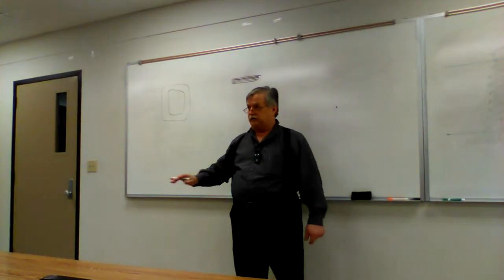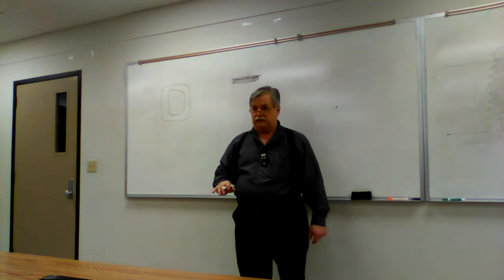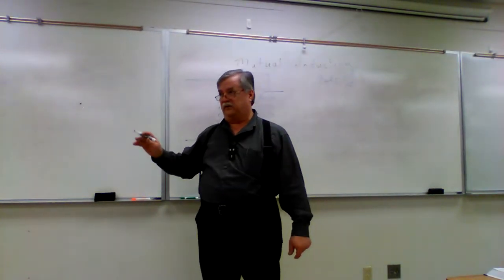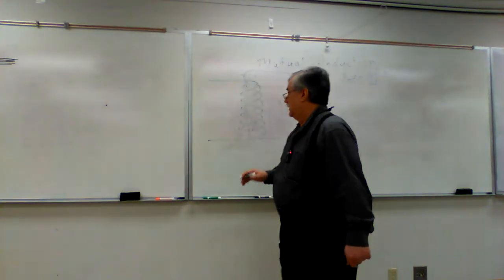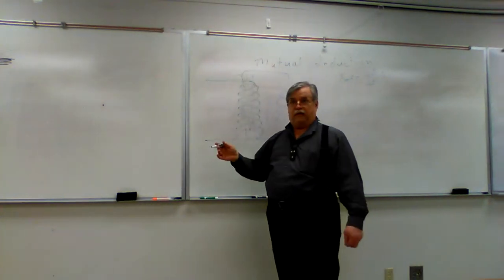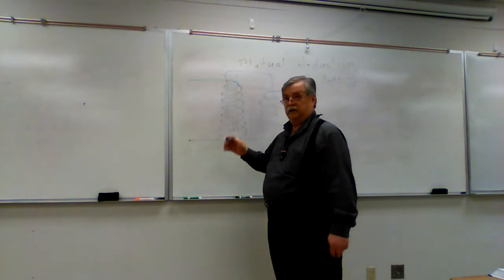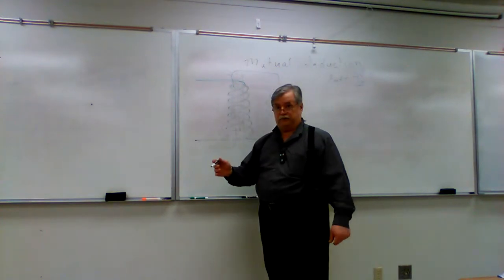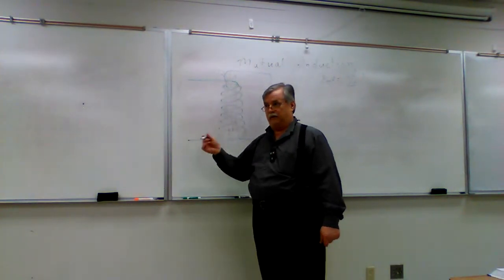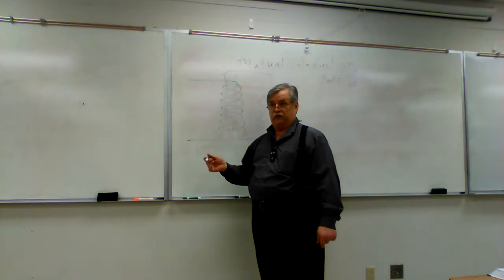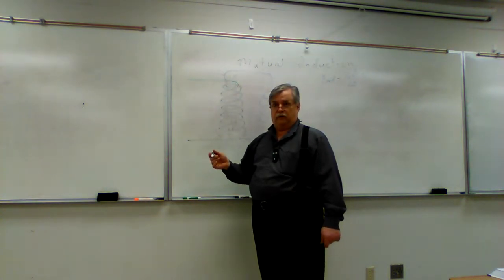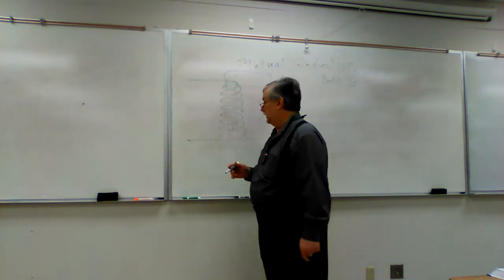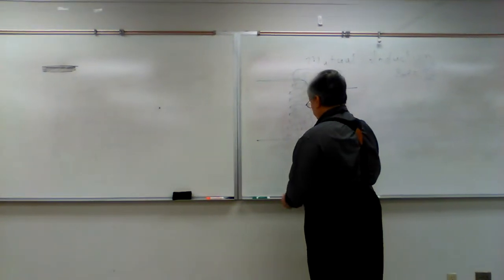all of those eddy currents to stay in these two-dimensional planes and minimize their effects, minimize the losses due to them. And like I said, we're not going to go into the math of it, but you can literally make these things much greater than 99% efficient. So for our purposes, doing the math on how to use these transformers, we're just going to assume that they're 100% efficient. In reality, they're never going to be quite there, but you will find that they can get very close.